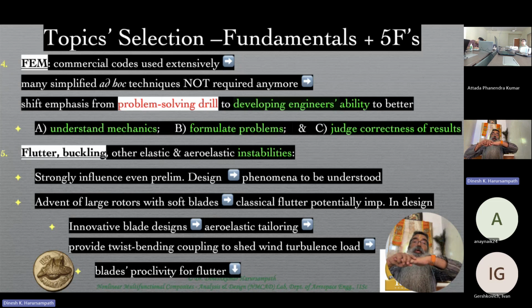And this is possible not only from the geometry of the design, but also from the material of the design, especially when you go to composites and you have layups, which are laminated structures with different fiber angles and different layers. When you go to those kinds of structures, it is possible for us, the designer, not because it's happening by itself, but we are designing for it, we are asking for it, and therefore we can design certain favorable couplings like twist bending coupling that is mentioned over here,